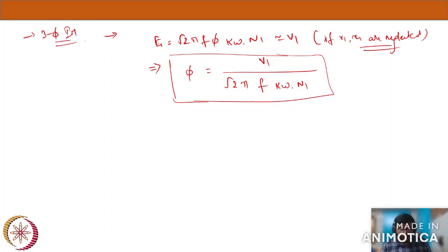I hope you all agree, because this particular flux per pole, if your circuit is open or closed, your flux in the core should remain the same. Because the flux you are giving to magnetize the core is always there, and you need some flux. That's the value you are seeing here. So this flux per pole should remain constant.